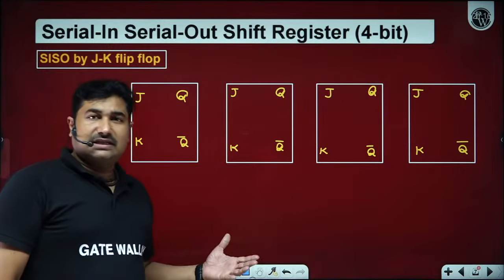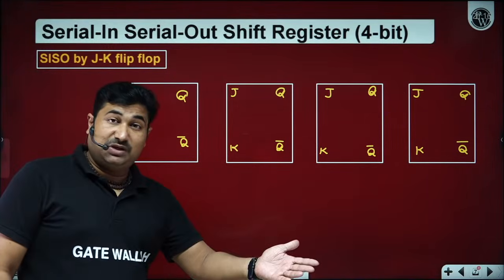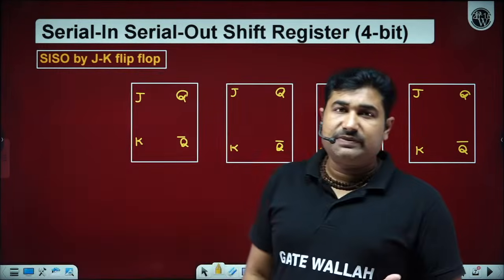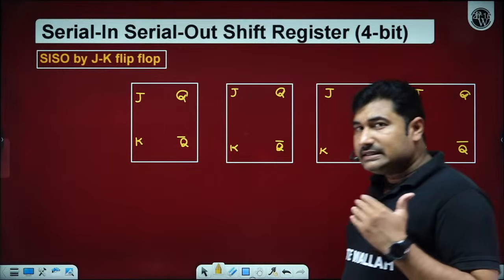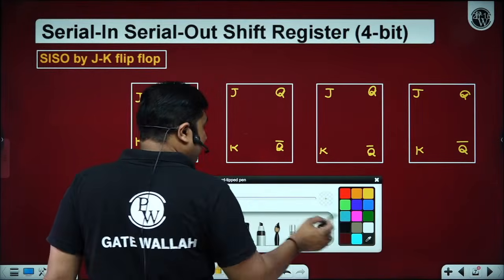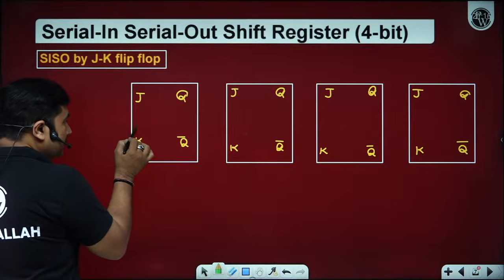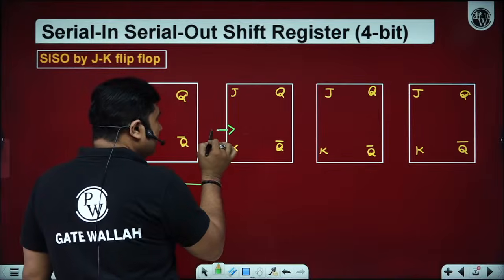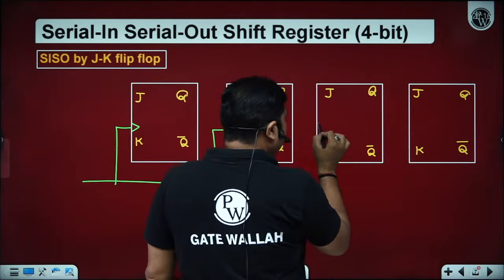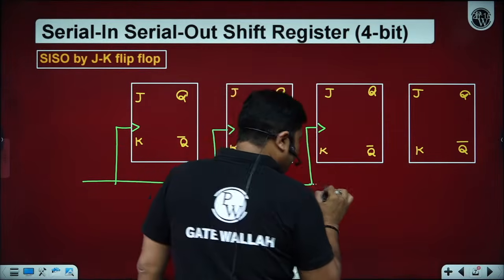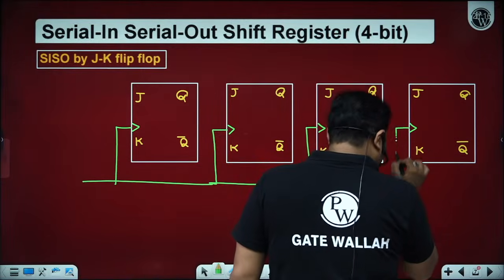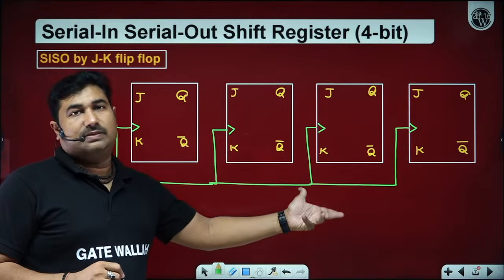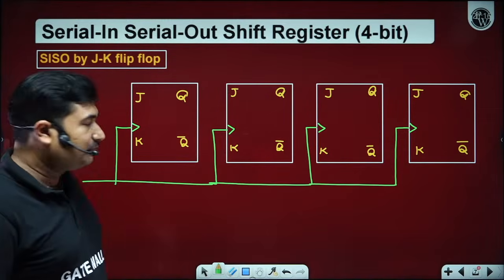In a shift register, unless we define the MSB or LSB, you can't identify on your own which one is the MSB and which one is the LSB. The reason is that all the flip-flops are connected to the same clock pulse. So you can't identify which is the MSB or LSB unless the designer lets you know. Up to this part, everything is clear?